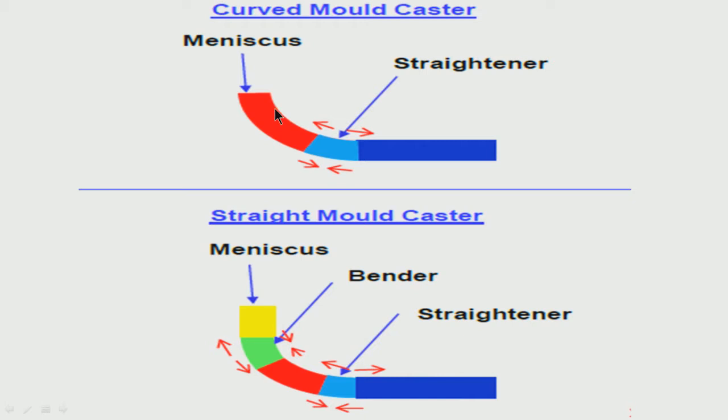Certain portion near the inner radius we will have more inclusions, we will have inferior quality in these areas. But if you have a vertical mold, that possibility is not there, it will be relatively uniform, whatever inclusions are there will be relatively uniformly getting absorbed in the solid shell.